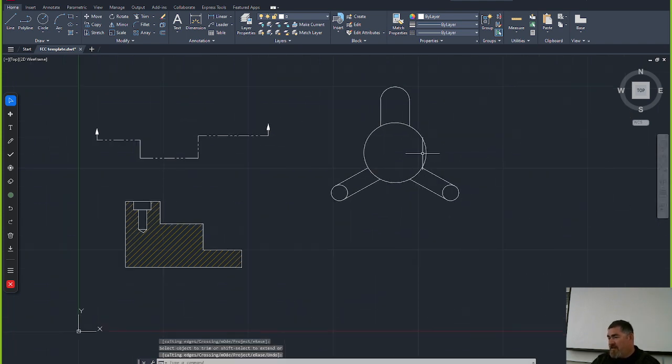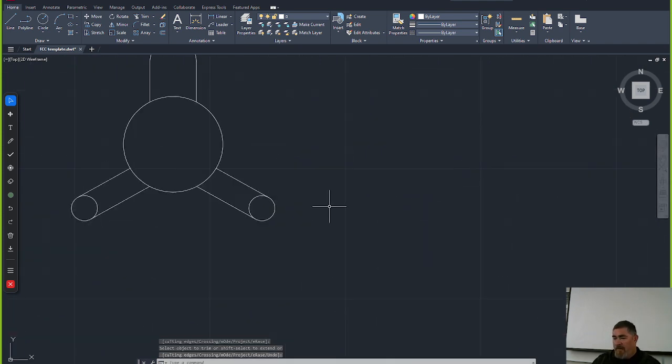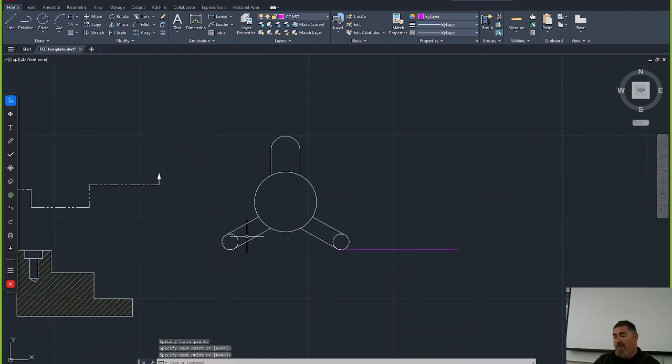So if I want to project over to the side from here, can I just pick my lines and come down to the quadrant and come straight across here? So let's say my cutting plane line is going to go from there to there, and up to there. So that's my cutting plane line. Can I just have that come straight across to project the other view?